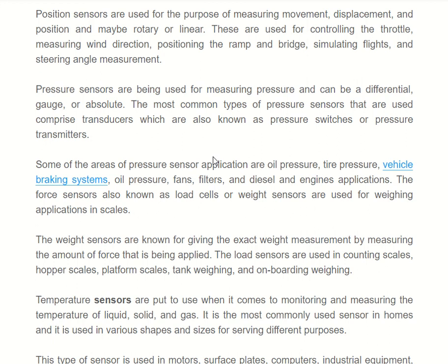Now the force sensors are known as load cells or weight sensors, which are used for weighing applications in different scales. They provide us the exact weight measurement by measuring the amount of force that is being applied on it. And the load sensors are used in counting scales, hopper scales, platform scales, tank weighing, onboard weighing. So in all these applications we use the weight sensors.